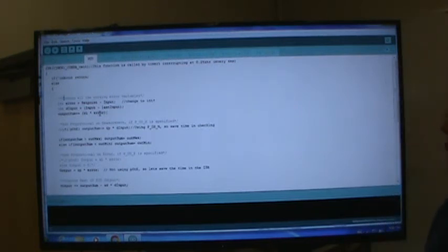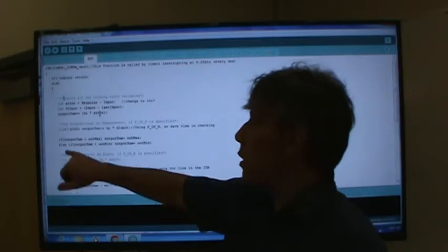And there is one change from last time. I changed error and D input to integers instead of doubles, trying to get the code to go a little faster. If you think about it, we're measuring position on the carriage. It's always integer numbers, right? There's never a need for a floating point or a double number. So just using an integer is fine for these variables, and I think it saves some time. I don't think I actually measured the difference on that part. I just assumed that a double would take longer to process than an int.